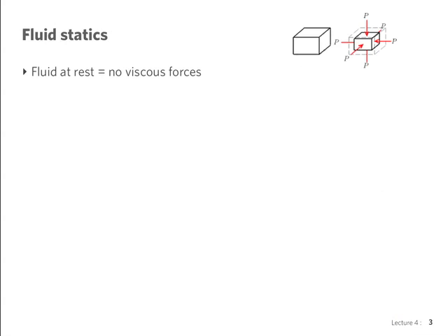Okay, let me go back here because I have something more to say. You can also write, I just didn't leave enough space, delta P. Still, we're talking about an incompressible fluid, so rho is equal to a constant, so we have delta P, say P1 minus P2 equals gamma H. This is rho g here, gamma, with H equals Z2 minus Z1.